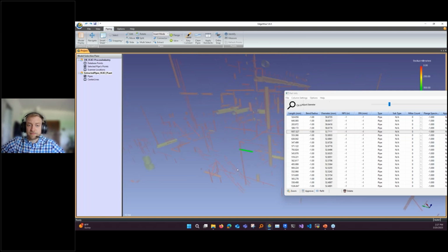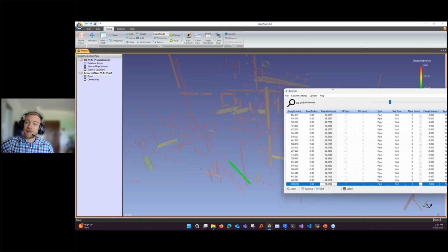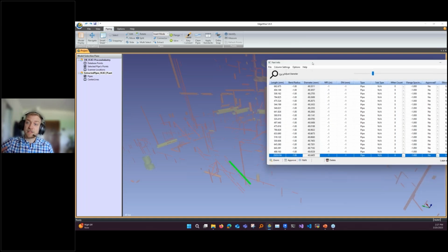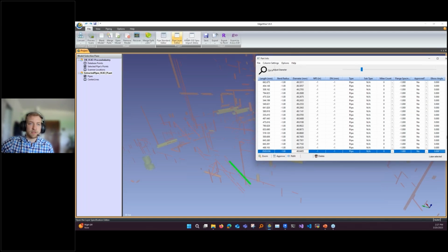Same thing for railing. In this case, that's another one we can just get rid of. Now, we can get really fancy where if you want to keep some of the geometry, there's ways to split the model up. And that one's a little bit trickier. That's really the advanced stuff, and I'll talk about it, but this is going over what you could do and what things are impossible in EdgeWise. There is a split based on layer tool, right?